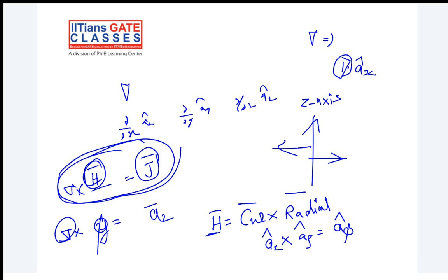Because if you take phi, radial again, direction. Yes, in the radial direction. That's what I was saying. If you take phi, your current density should reflect 0, because you are saying the current is in the z direction, so your del should accordingly be in the direction of rho, the radial direction. Understood. I just had confusion in this. Okay, sure.